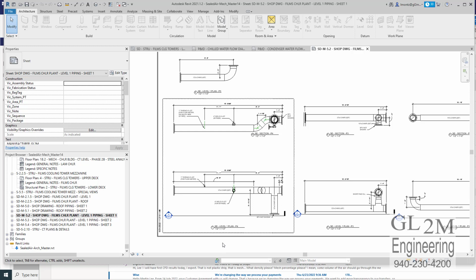And we develop assembly drawings of the various components that need to be built for this chiller plant, and the contractor can weld them all up in his shop. And it turns out when you're welding stainless steel, that's more important than when you're welding carbon steel, because if you're welding stainless outside in a windy environment, it's hard to keep the high purity gases around the weld, and the quality of the weld suffers. And this way, they're going to build these assemblies in their shop, truck them to the site, and then bolt it together on site. It goes together faster.